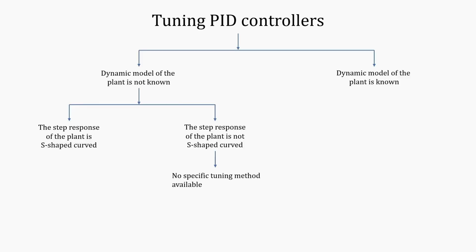I convert the objectives into desired pole locations, and once I have them, I draw the root locus of the open loop transfer function and see whether the root locus passes through the desired location. If it does not, then I design a PD controller or a PID controller depending on the problem, and then I adjust the gain such that I reach that location. This was the method that we have done till now.